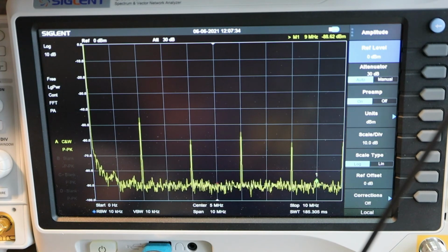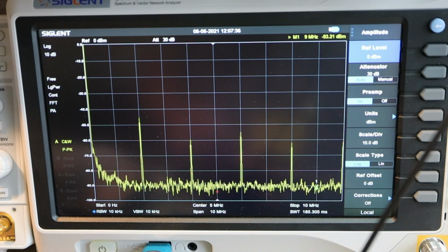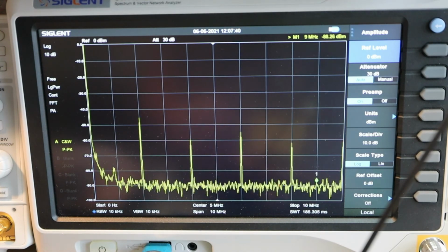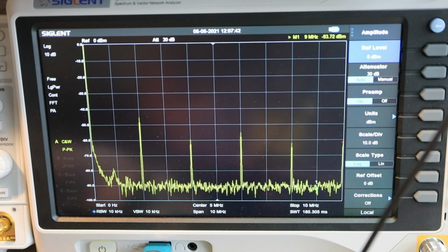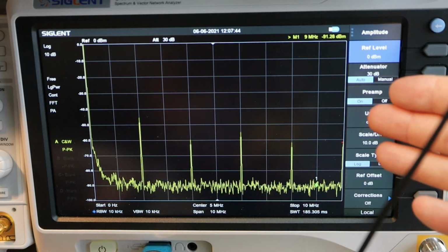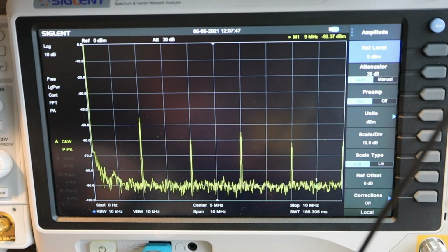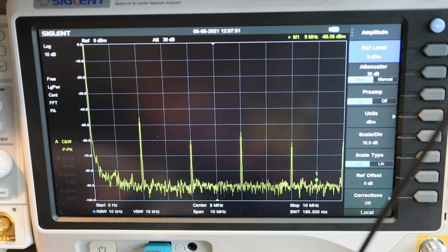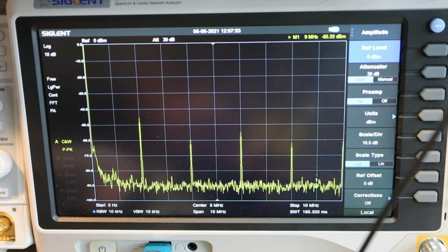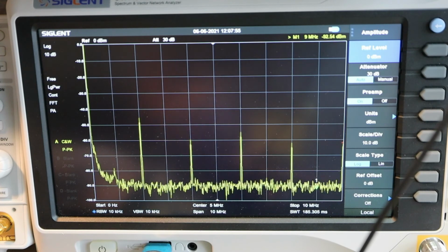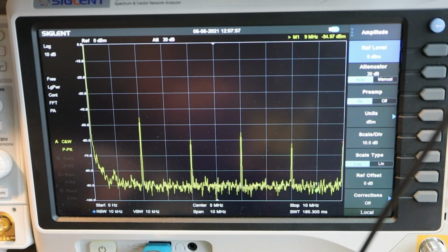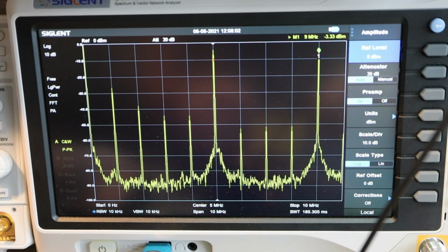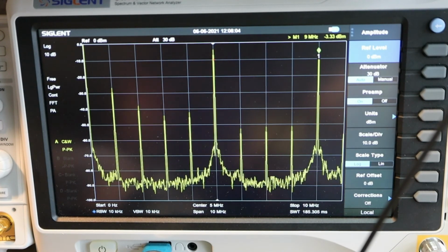So we don't like that, because these products get mixed again, maybe reflected even. And if you don't have a proper termination of your mixer, all these spectrums should be terminated by 50 ohms. So you should have 2 megahertz terminated by 50 ohm and maybe 20 megahertz as well. And if those are not perfectly terminated, then they reflect back and get remixed with other signals that are around. And so that can cause some problems. So the SBL was definitely better there.